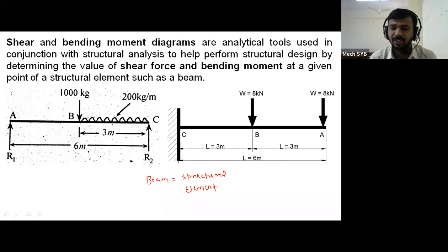If you see our construction, in that construction, so many structural elements are there. For example, column is there, beam is there, then slab is there. So by combining all these structural elements, your construction is finished, or you will get one room. If you see our room or our home, in that home, slab is there at the top side, columns are there in the vertical direction, beams are there in the horizontal direction. So these are the structural elements which are designed for the particular load.